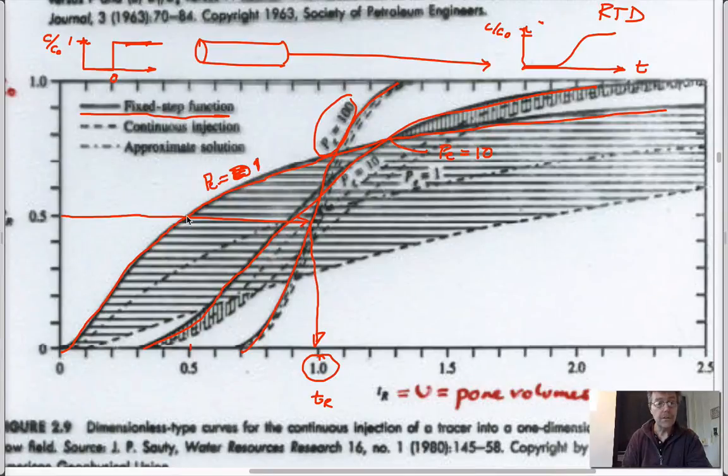And so the important thing is to realize that we cannot always take the fact, as you've done in your calculations so far, that advective velocity is equal to length over time. That certainly is true, but we can't always use this to give us the time at which it arrives, which is equal to the length traveled divided by advective velocity. Even in the average, right? It's true in this case, because here it's basically at 1 pore volume. But if you use this calculation, this is the arrival time of the plume downstream in terms of the 50% concentration.